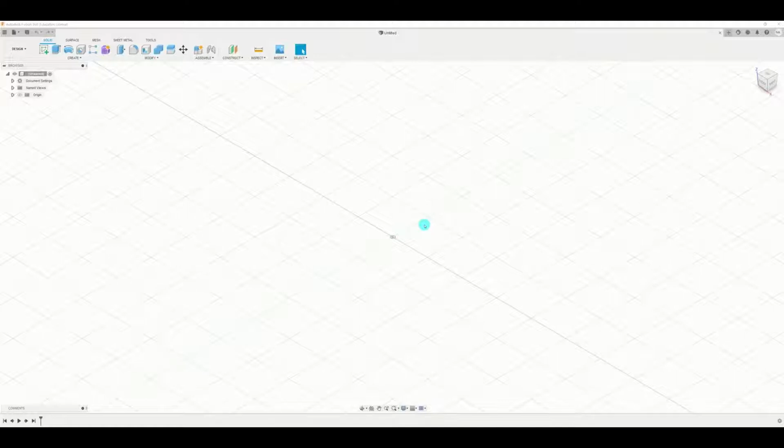So first is, of course, you open your program by clicking Fusion 360, and you'll end up with a blank screen like this. So the next thing to do is we create now our design file. Now what you see on the screen is really for the workspace that you use for drawing 3D objects, and later we will use this when we are making 3D objects such as the casing of the board.